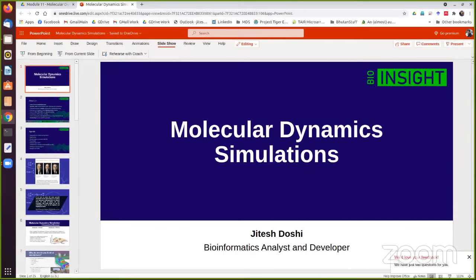The simulation also outputs the EDR files. These files contain different types of energies of your molecular systems and groups, so those can be tracked. For plotting and checking the energies, the graphs and all that, you can use the EDR files. These EDR files can then be converted into the XVG format, which is often used by programs like Xmgrace to plot the data on a graph.